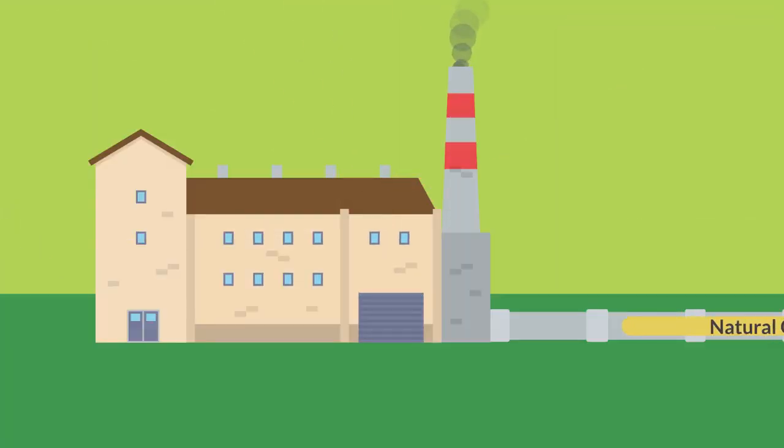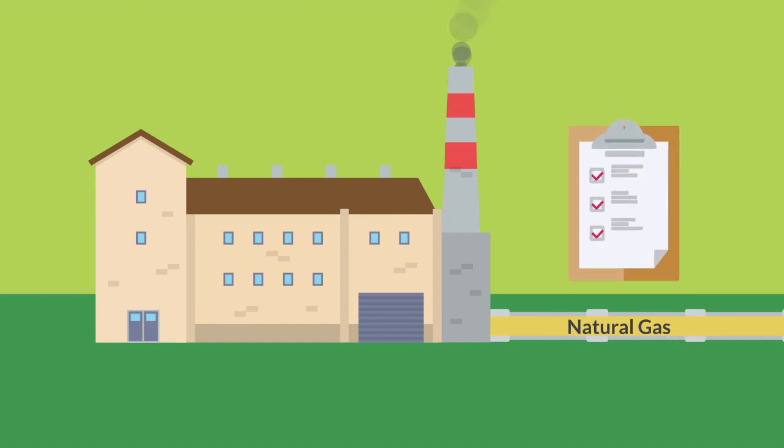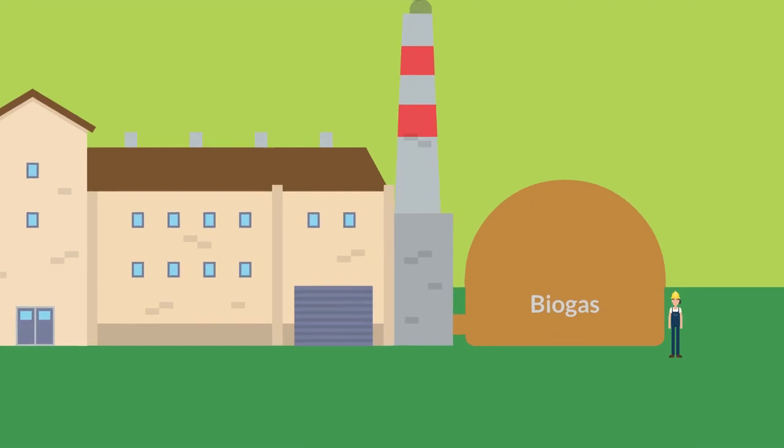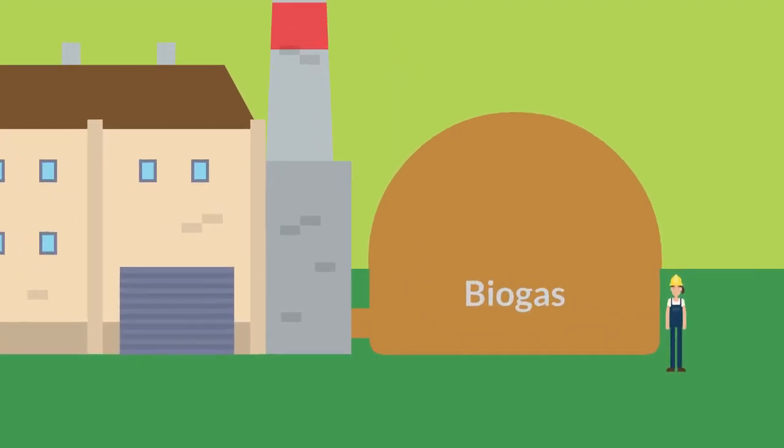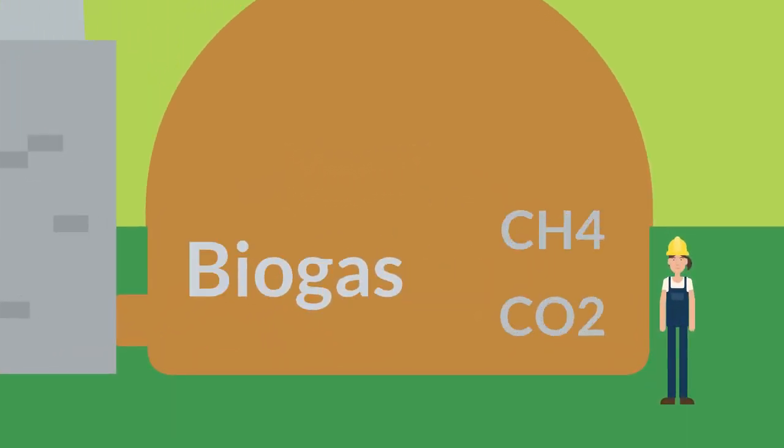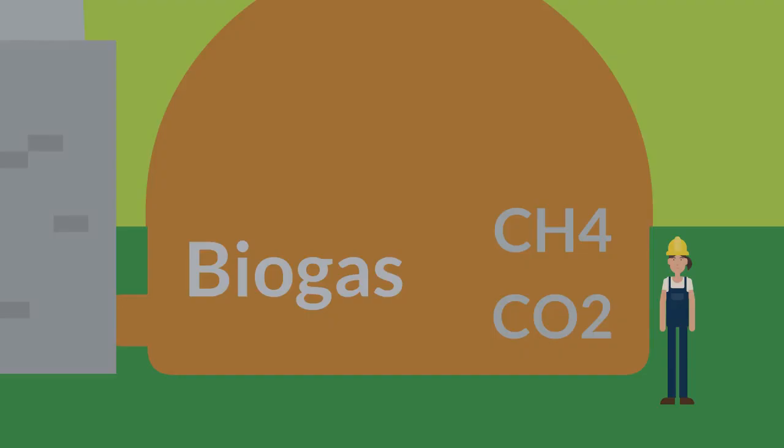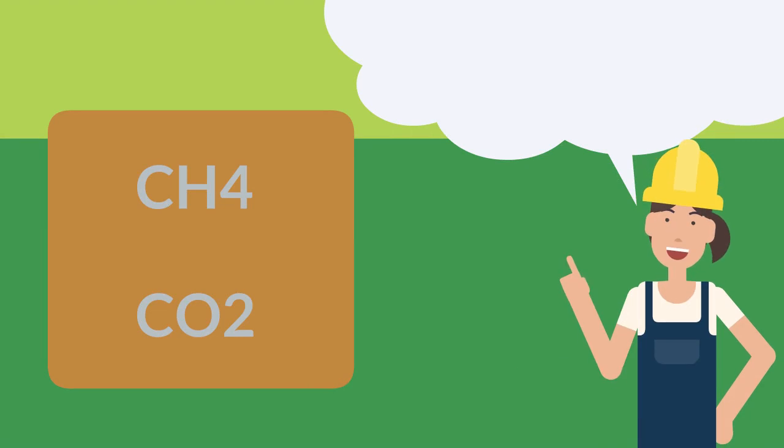When using natural gas, Jane has used the data from the company to know the heating value. Even when working with biogas, it was not so difficult. Making an analysis of the gas composition, she could easily calculate the heating value of a mixture of gases. Just multiplying the heating value of each component by its molar fraction and making the sum for all components was enough to calculate the heating value of the mixture.